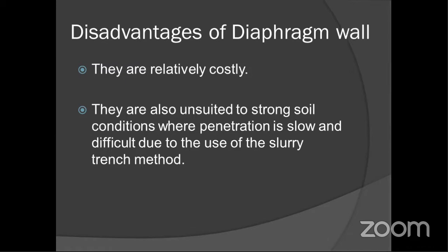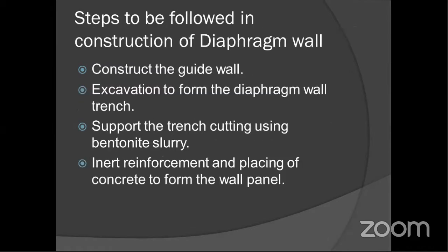So that will become costly, and it will become a very slow process to conduct. See, if we are going for the construction of diaphragm wall, we have to follow certain steps. First, we have to construct the guide wall. Then we have to go for the excavation for the diaphragm wall, and after the